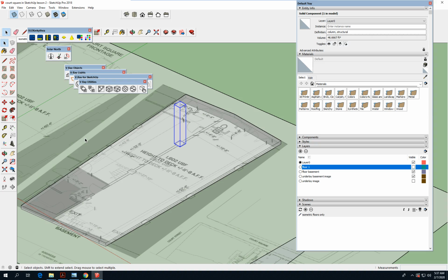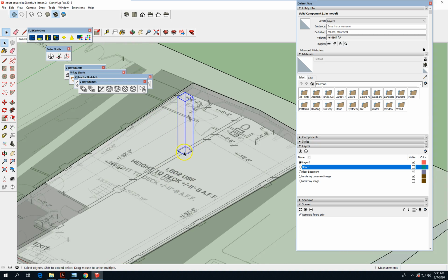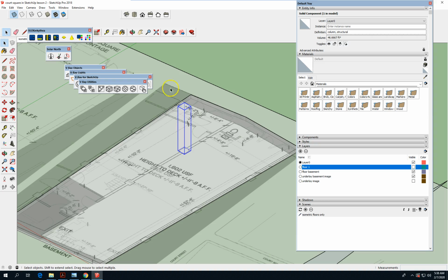Now, in most buildings, the columns in the basement are more massive than the ones above. They're usually more slender as you climb through the building. As you go on upper floors, the basement may use some kind of massive concrete pilings, whatever. Upper floors may be steel, and then they enclose those in some kind of fireproofing material, and then furring walls.